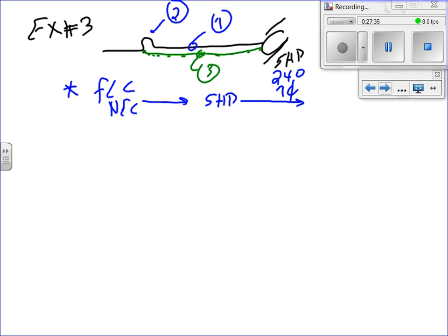and let me just rearrange my stuff here so I have room. We say 5 horsepower, 240, single phase. The first thing you do, guys, is find the full load current from the NEC. What's the full load current from the NEC? The acceptable full load current based on the NEC. For motors, guys, they give you the full load current from the NEC.